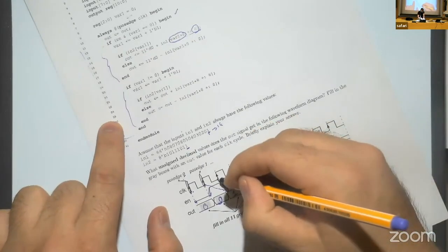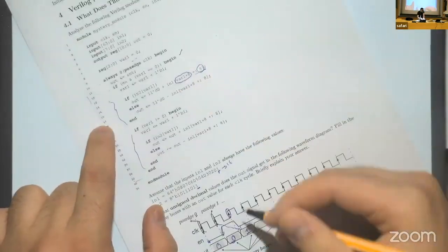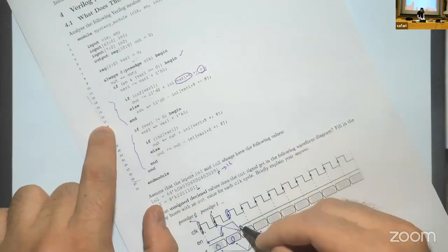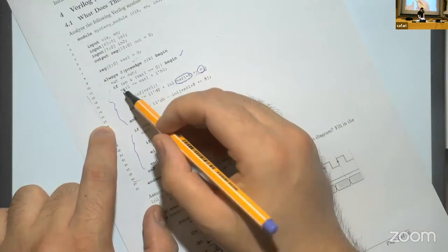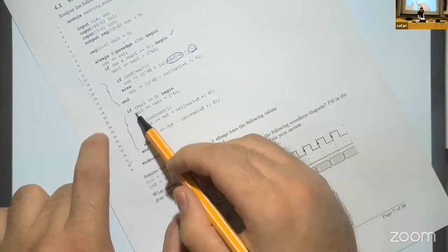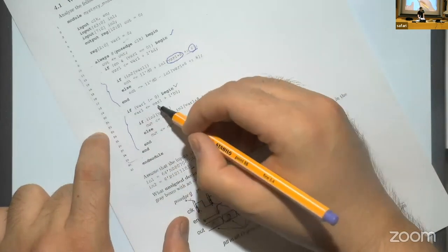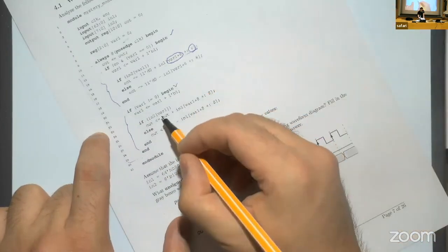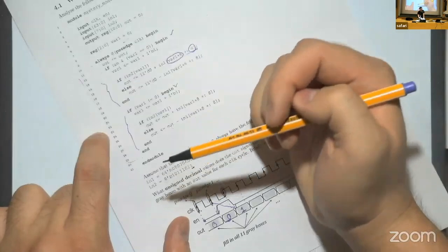So when we execute this one, var1 is 1 now, and out is 1. Let's execute that one again. Enable is now, it doesn't matter, variable 1 is 1, so we don't go into that block. And we check this if, the 21st line. Variable 1 is not 1, so now we go into that one. Variable 1 becomes 2 here, but it will be updated after this always block has executed.